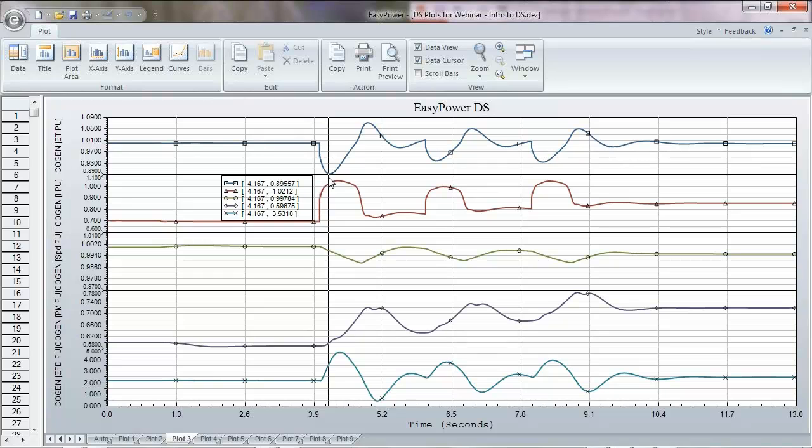For this system, we dip down to just under 90%, at 89 something, and then we overshoot to 107, so that means we're at 107% voltage for that brief moment in time due to a motor start. And this is a very, very common behavior. I've done measurements on large ships that have isolated power systems. I've seen these voltage responses show up on the bridge, on the 120 volt outlet, because some large motor was starting over and over and over again.